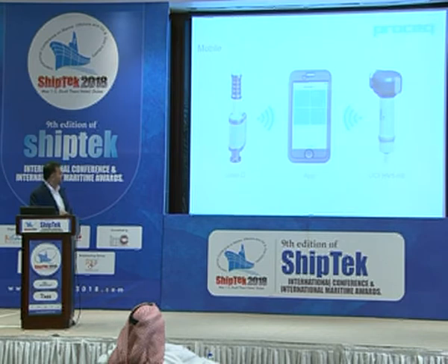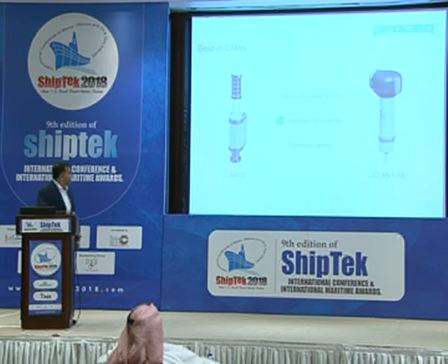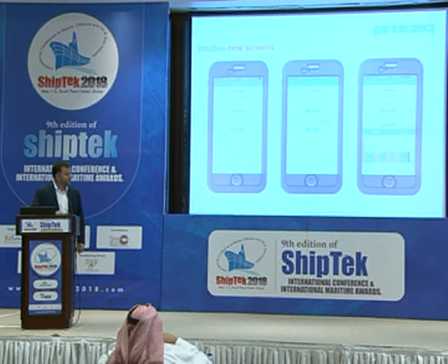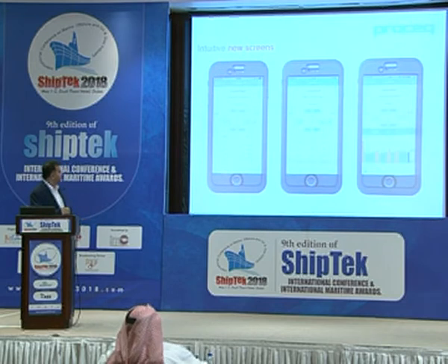So the good thing is via Wi-Fi, the Bluetooth, it connects easily, and then with the app we can start using the instrument. So multicolor status LEDs after connection, standard AA batteries, so no issue of carrying it on board, and also its ergonomic design. This is for the Leeb technique, and this is for the UCI, the ultrasonic contact impedance, HV1 to 10, again with the selectable probes. So now it has been so easy and simple that on our iPhone or the iPod, we can easily select the material, select the curve, we can have an alphanumeric name, and then we can have all the data on the Apple device.